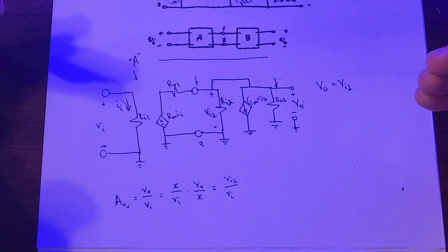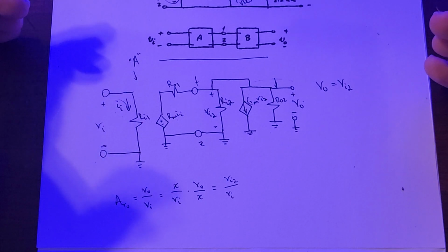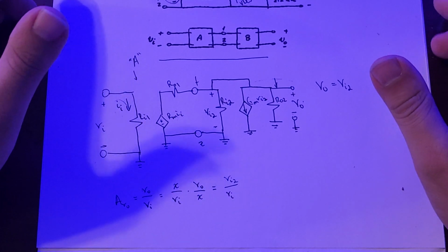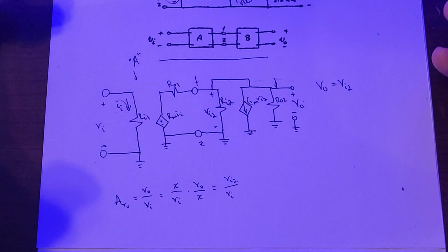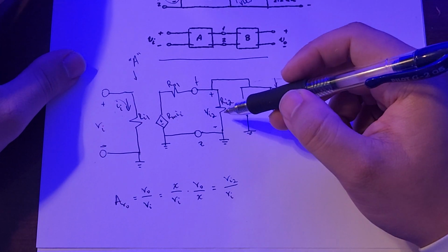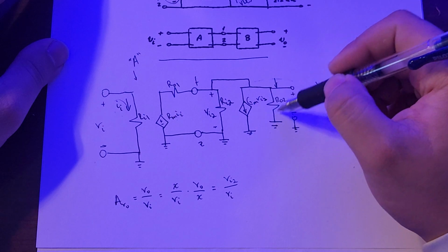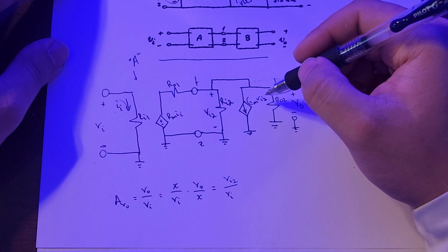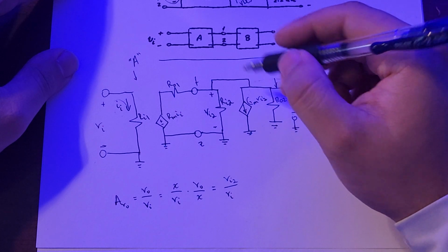we can solve for, I guess, some sort of open circuit voltage gain, or VO, using a node voltage if we wanted to. So what we can say is, let's see, Ri2 is here, Rout2 is here. So if we do node voltage, we would have to take this entire node.